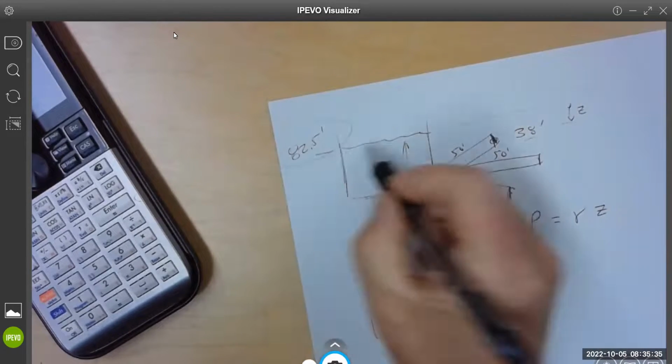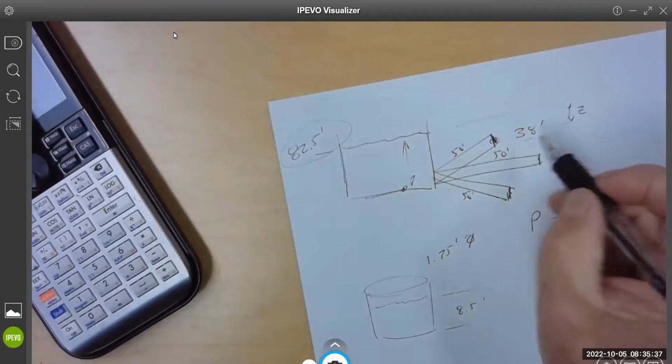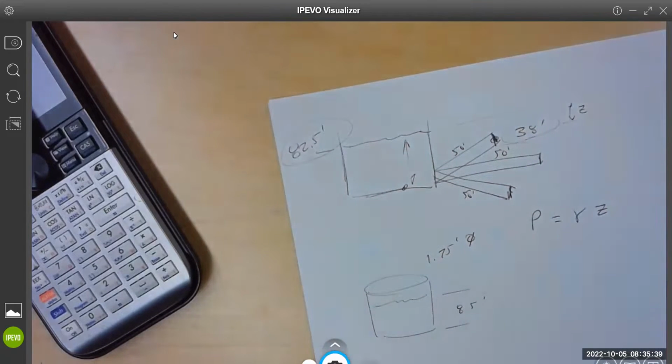So one of the things the book does a lot of is has a starting elevation and an ending elevation. So you'll get that a lot. It can be a little confusing as far as what the actual depth is, because they give you these different elevations. They're not trying to have you incorporate altitude into the problem. It's just the way surveyors do it. They don't use 0. They use whatever the elevation is, and then the second elevation. And then you just have to subtract between the two to figure it out.